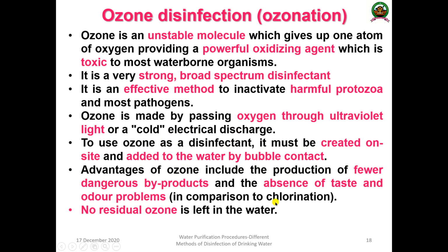by bubble contact. Okay, so that is very important. When you apply ozone as a disinfectant, it must be applied on site, and it should be added to the water by bubble contact, otherwise there will be a lot of issues.